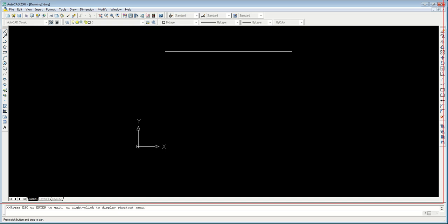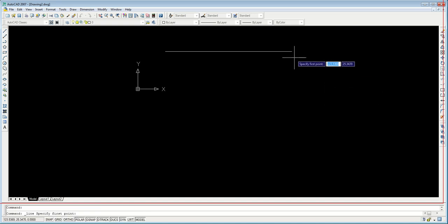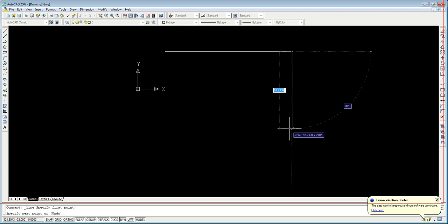So now after that I want to draw the other line. If I want to continue my line from the end of this, if I go to this line, I will see a small yellow box. This yellow box is the end of the line, so I click, and then usually we write the dimension, because the dimension, as you see, is 62 point, and there are 4 numbers. So if you try to fix it to 70, it will be very hard, and it will take more time than you think. So usually we write 70, for example, and enter.